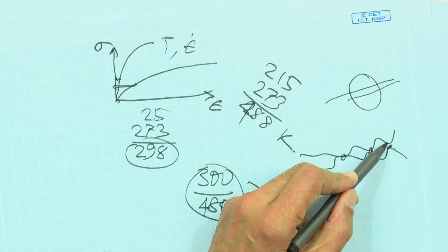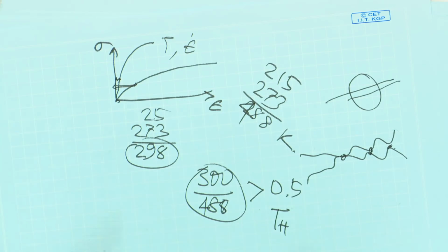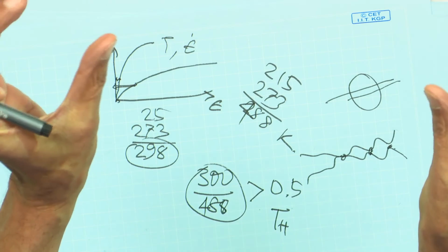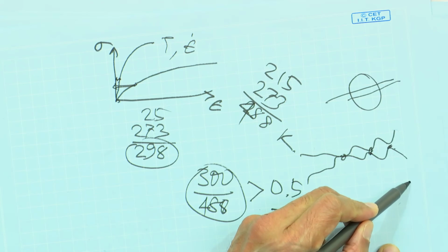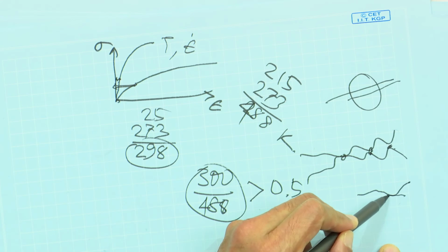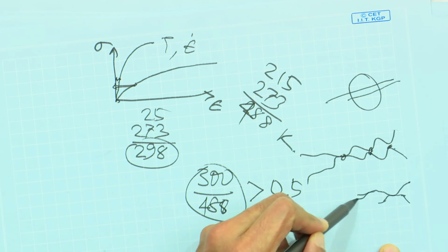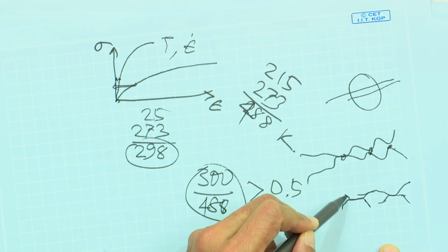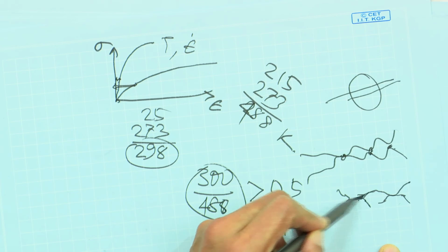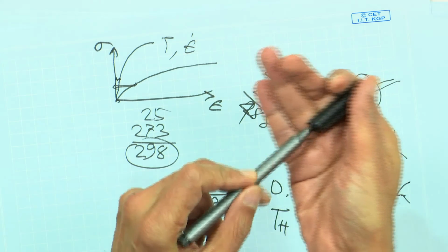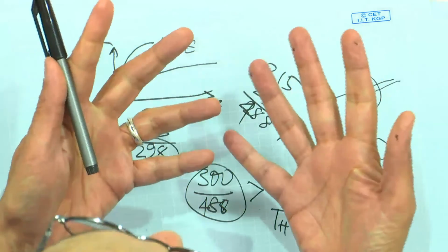On the other hand, if these are soft materials, and remember all connectors have some spring force in them, then under the spring force, all those contact points will start to yield. Okay, so if there's a soft metal, the contact surfaces will start to yield. So these points now become contact surfaces because of localized yielding. So that's why we need a soft metal on the surface. The second thing is gold is not just soft, it's also a noble metal. Prevents corrosion. So it protects the base metal from corrosion. So that's why high reliability connectors have these soft gold coatings on them.